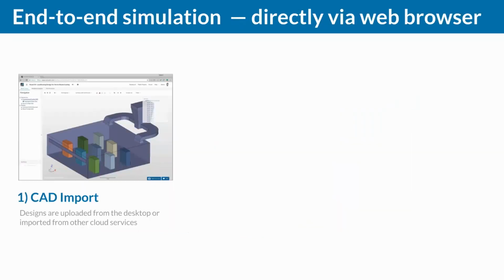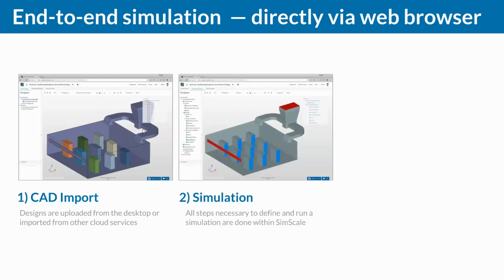So we have an idea, but now how am I going to run this simulation? First of all, you need the CAD model. So we import a CAD model into the software, and in this case we are using the SimScale platform. We import the CAD model directly from your CAD software, and as you can see here we have our graphical user interface. Then the second step is generating the mesh, doing the spatial discretization of the mesh. Then we apply the boundary conditions and so on.